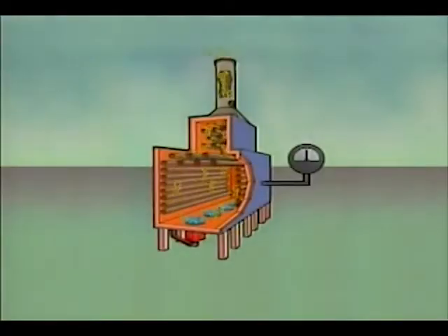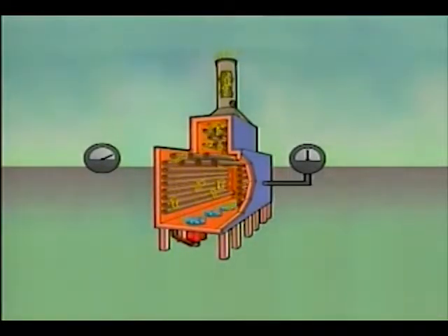In a natural draft furnace, the hot combustion gases, which are lighter than the outside air, rise up the stack and create a lower pressure in the furnace. As this occurs, cooler, heavier air from outside the furnace is drawn into the burners through the air registers. Airflow through a furnace is produced by a difference in pressure. In an operating natural draft furnace, the pressure inside the furnace is less than the atmospheric pressure outside. As a general rule, as the difference in pressures increases, the amount of draft in the furnace also increases.